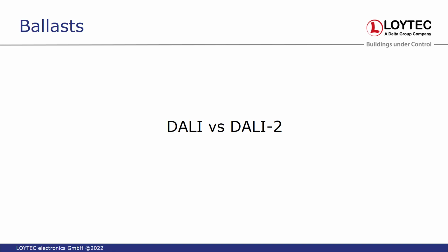Yes, I think the point is here what DALI 2 is doing and what Hans showed at the beginning of the presentation. In DALI 2, you have the possibility to have a standardized test. For DALI 2, there is a test fixture and there is a number of tests that you need to execute with your ballasts. This is some timing issues.